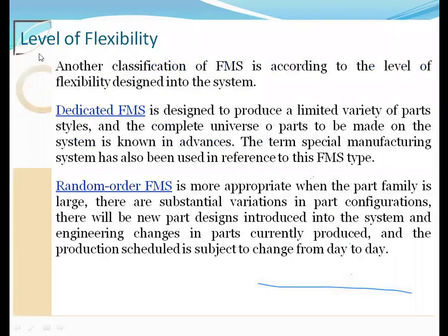Next one is level of flexibility. Based on the level of flexibility, there are two types. One is dedicated FMS. Second one is random order FMS. What is this dedicated FMS? The name itself indicates dedicated, meaning it will be dedicated for a particular part, or particular type of components, or particular type of operations. Random order FMS means it is not a dedicated one. It can be used for other varieties of machining.